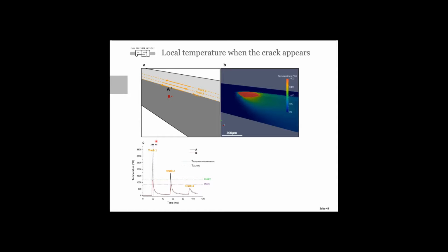So typically at these boundaries, we get a small liquid film, and because there are always tensile stresses in this material, we create a crack. So we create a so-called liquefaction mechanism. Now you may ask the question, yes, but this comes from simulations. How do you know that these simulations are correct?